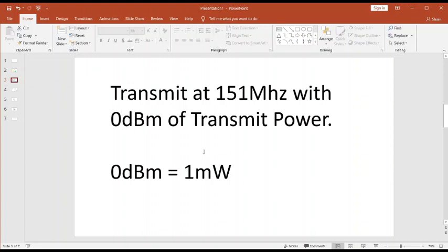It's simpler to do adding and subtracting than multiplying and dividing. And when you convert everything into dB units, when you go through an RF chain, you simply are then adding and subtracting the dBs. Okay? If I have an amplifier that has 30 dB of gain, and assuming it can go out up to a watt of output power, if I put in 0 dBm, I simply take 0 dBm and say plus 30 and say, oh, the output power will be 30 dBm. So working in dBs is simply adding and subtracting.